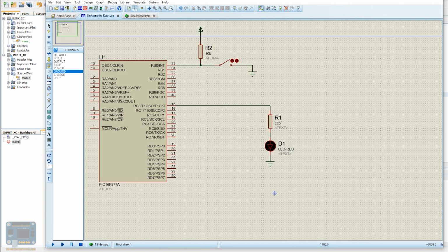What happens here is, if you press the switch, your pin will be connected to ground. And if this is open, your pin will be high, since it will be going towards your positive source. Now the resistor is here so that when the switch is turned on, your positive source and your ground will not be shorted out, which would be trouble for your circuit.